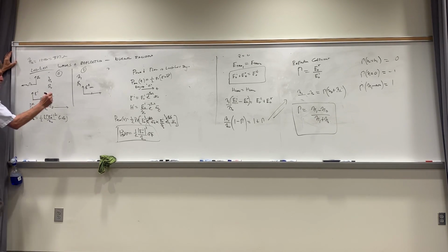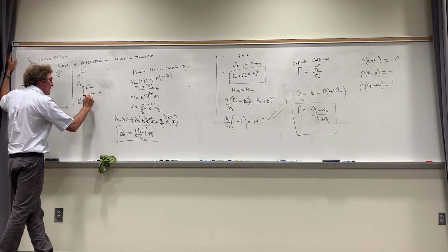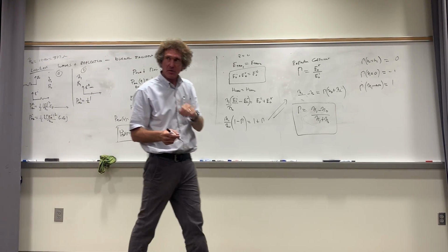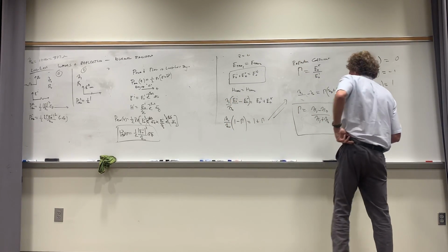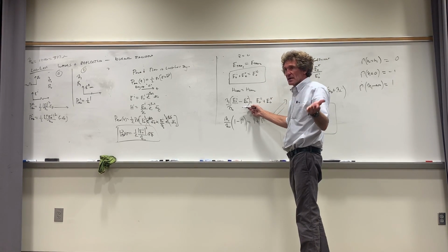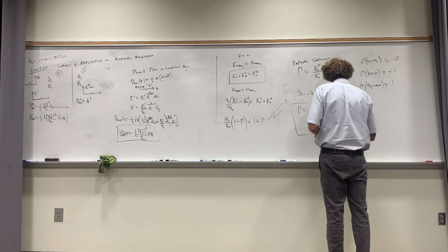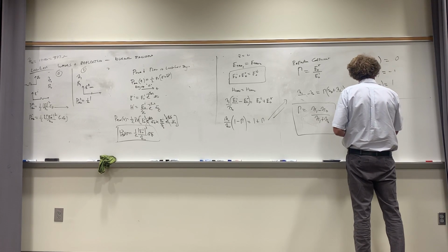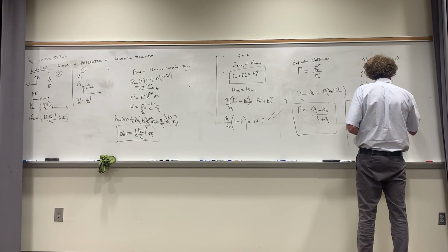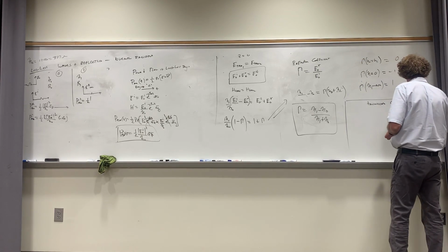Now we've got transmitted power too. And P av transmitted will be equal to 1/2 magnitude of the transmitted field. This I didn't talk about yet. I got the reflection coefficient. I want you to see something. I can manipulate these two equations, this equation and this equation, and I can get a transmission equation, transmission coefficient, all right? And here's the interesting thing. Please write this down in the corner here. The transmission coefficient, the symbol for that is tau.